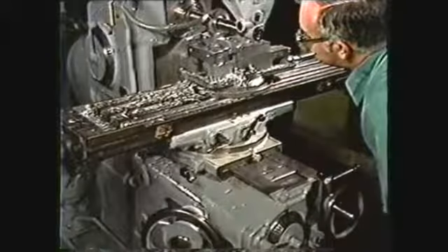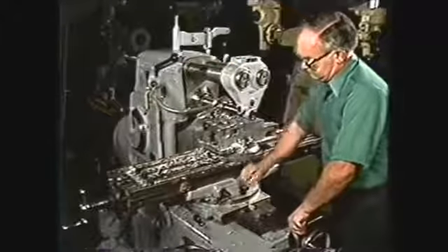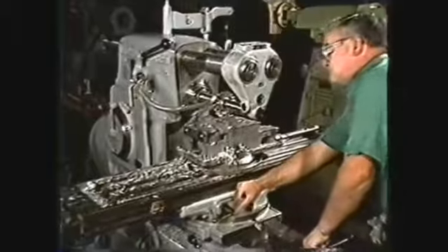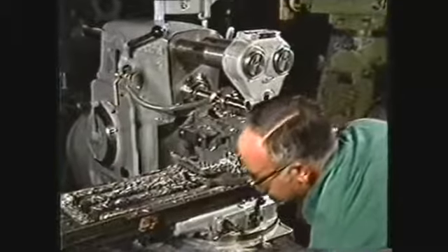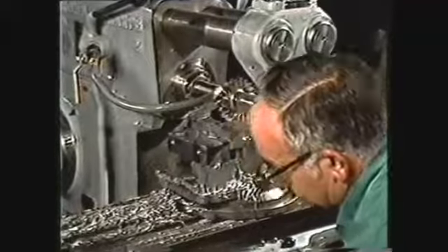When the first pass through the groove is completed, shut off the spindle and use the rapid traverse to bring the table back to the starting position. Never use the rapid traverse to return the cutter when it is running. This could cause the cutter to dig in and gouge the work.